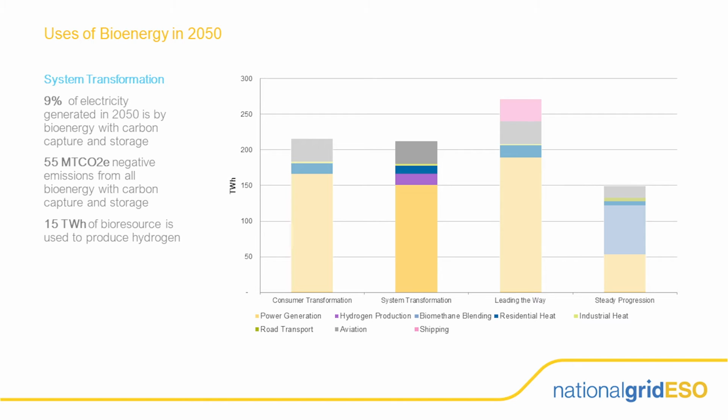The increase in negative emissions is largely down to hydrogen production from biomass combined with CCUS. This is done through a process called biomass gasification, a technology that uses a controlled process involving heat, steam, and oxygen to convert biomass to hydrogen and other products without combustion. During this process, the carbon extracted from the biomass is captured and stored, resulting in negative emissions. The additional negative emissions are required to counter the residual emissions from hydrogen production from methane reformation with CCUS.